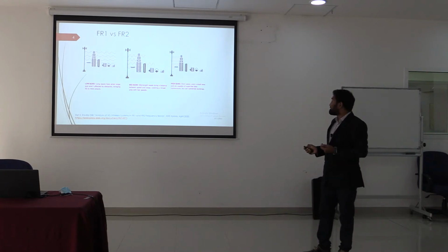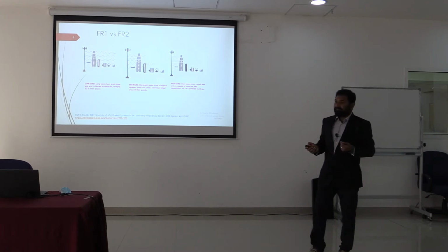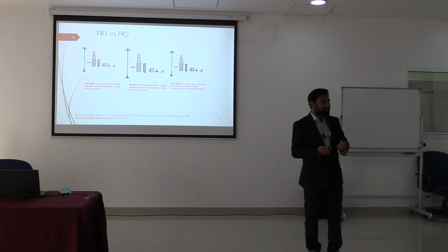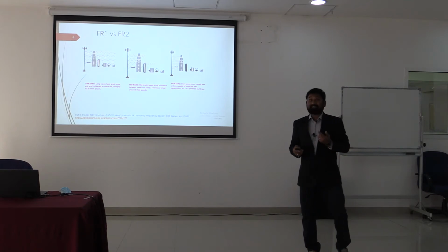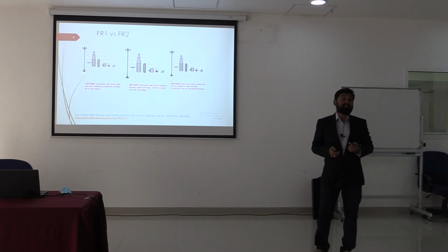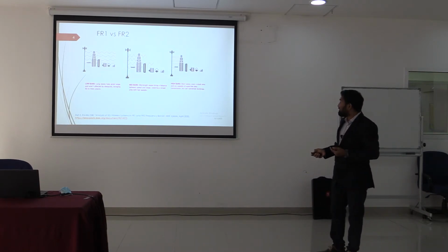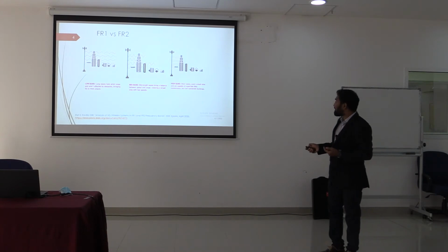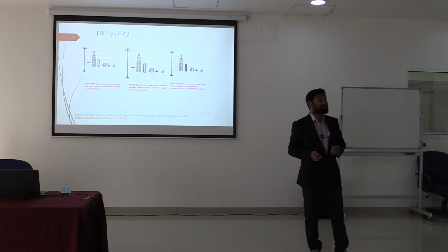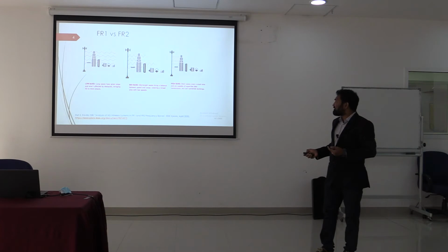So in the comparison between FR1 and FR2, from the 700 megahertz spectrum to the millimeter spectrum, we can have a large coverage area, but the speed has to be balanced. So the ITU-T, the International Telecommunication Union Telecommunication Sector, has been recommending a new frequency spectrum in the mid band, very close to your C-band application, 4 to 6 gigahertz, with 7.125 as the upper frequency for 5G application.